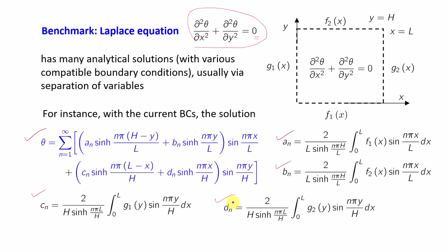Now this looks pretty intimidating, but you don't have to take all non-homogeneity at the same time. You can pick one by one, have this solution, and then match with your PDE solver, your numerical solver. So this is one benchmark problem. I'm not claiming this is the only benchmark problem, or that this is the best benchmark problem. Actually, similar to this, we should match with several benchmark problems. Then we will be reasonably sure that if our solution matches, our solver is doing good.